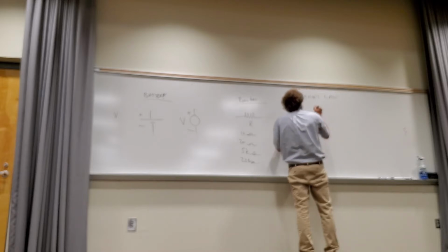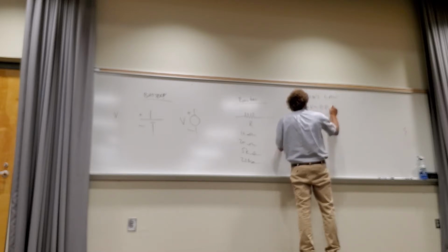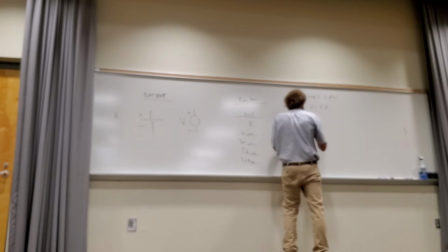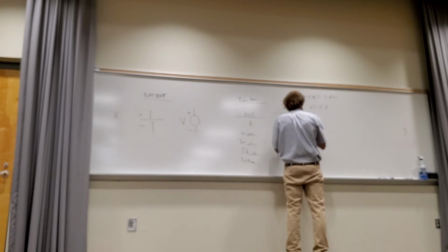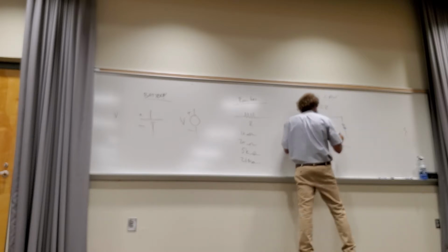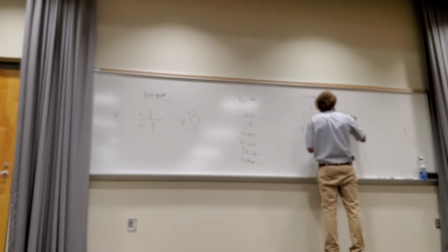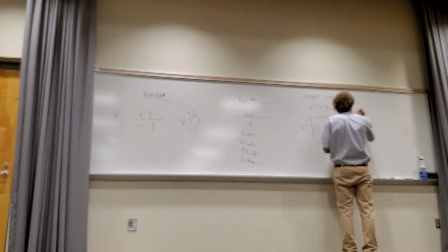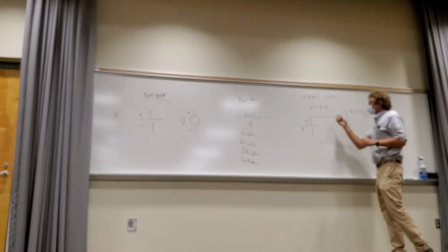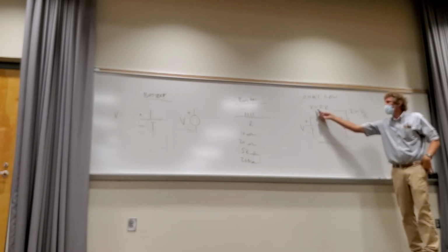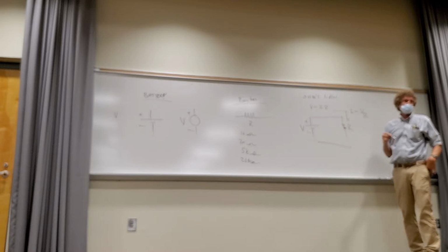And it says this, and I'll explain. V is equal to I times R. I'll try to keep it as simple as possible at first. So, if I have a voltage source, V, and I connect a resistor across it, R is the resistance, the result is a current that flows from the positive to the negative terminals, I, and I is simply V over R based on this equation. V equals IR, that means I is V over R, right? If I have two of the three things in this equation, I can solve for the other. Do you all see this, class? Now this is basic physics, correct?